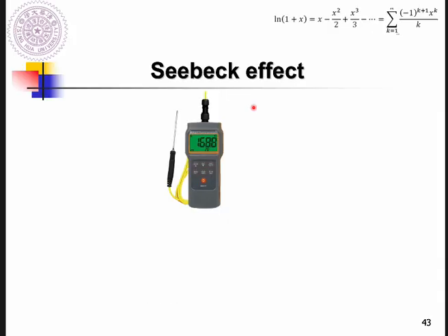And the other, let's move to here. Even though you have some idea for power generation as the application of the Seebeck effect, another application is the thermocouple, also based on the Seebeck effect. So this is what you usually use in the lab to measure the working temperature in the furnace or anywhere. Okay, you use the thermocouple to measure the temperature.